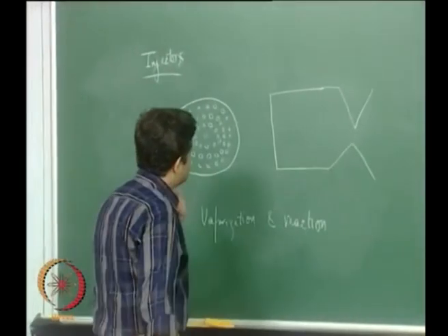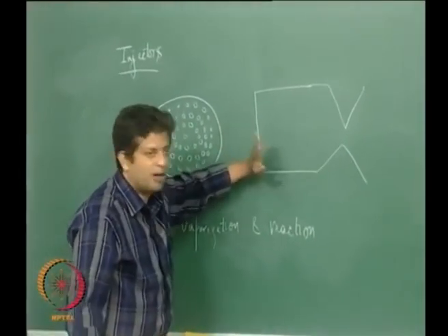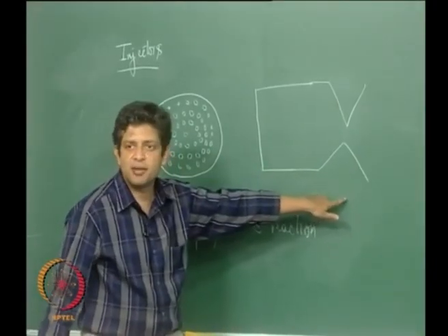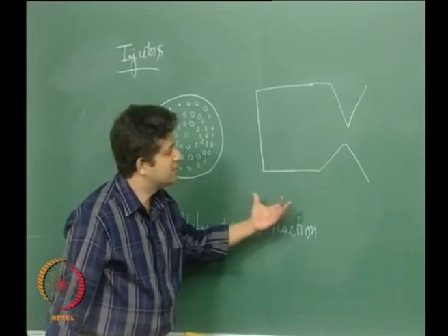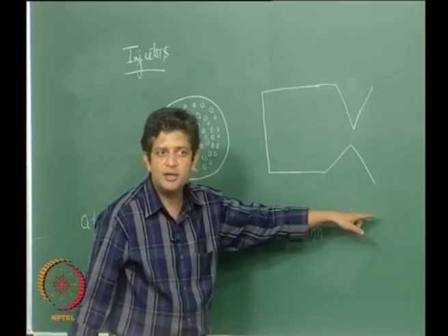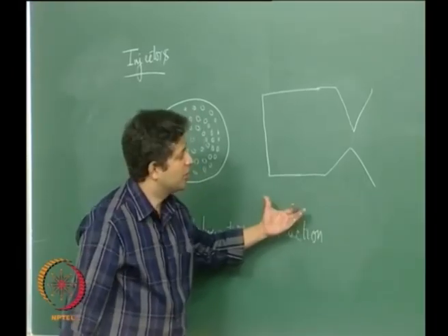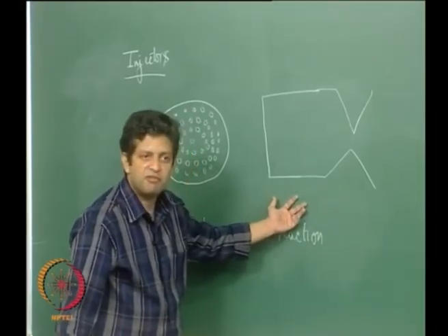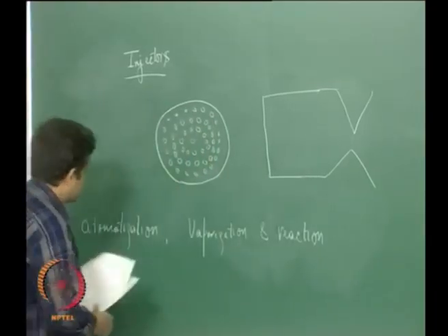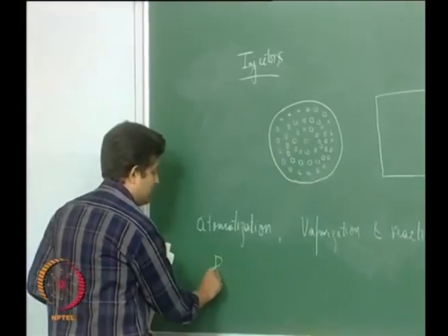Typically what happens is, these liquid droplets are coming in. One can define something known as a residence time. Residence time is nothing but the time that is available for reactions to be completed, or the stay time of these fluids in the combustion chamber.